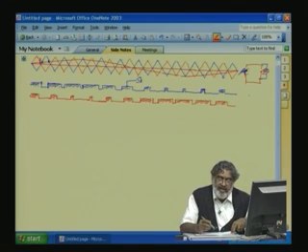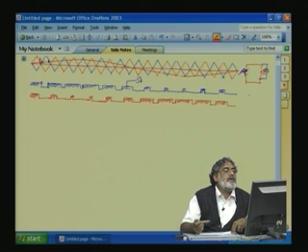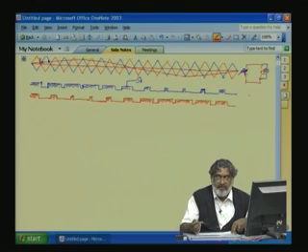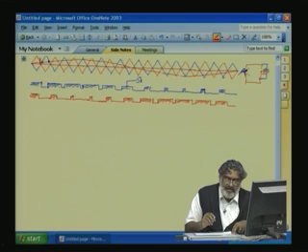So, what we have to remember here: the triangle waveform is one carrier, and for the other leg B it is the inverted triangle waveform. For leg A, when the sine is greater than the triangle, the top switch is on, and when the sine is less than the triangle, the bottom switch is on. In leg B, whenever sine is greater than the triangle, we turn on the bottom switch. The logic is inverted here.